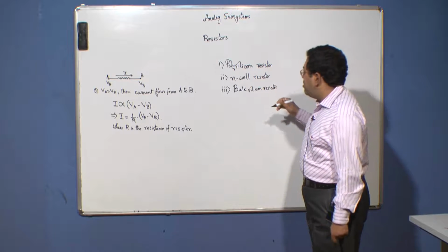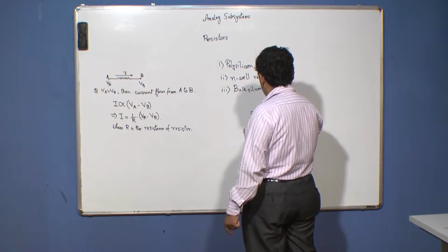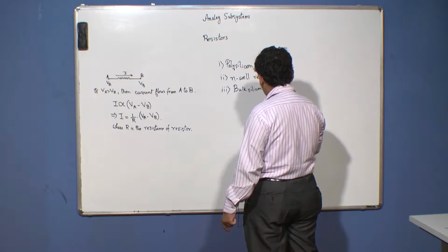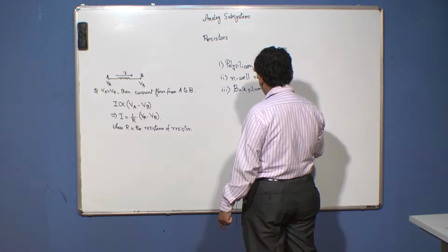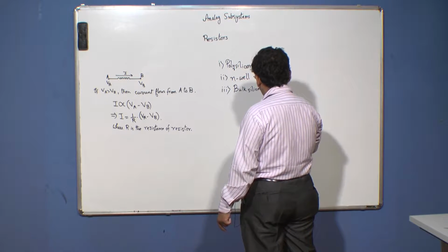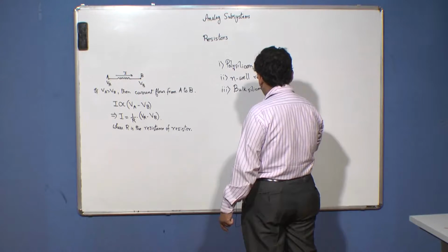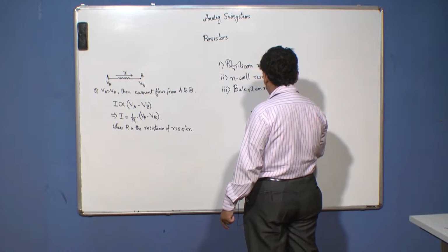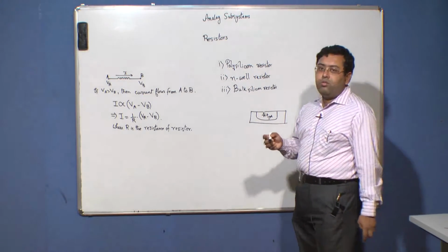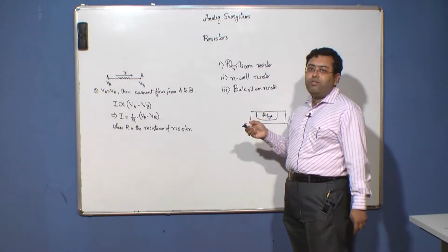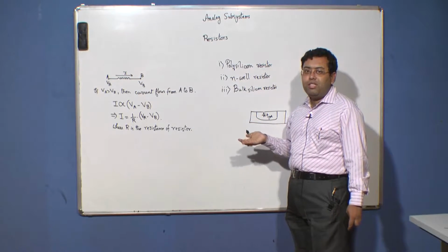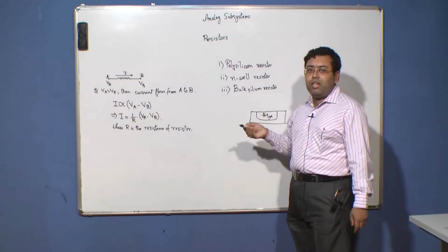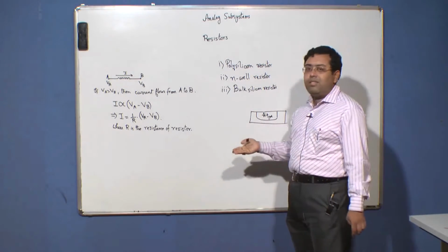We can have a doped silicon wafer, where a part is densely doped with donor impurities, and depending upon the doping density, the resistance is going to vary. That means, as you go on increasing the doping density, there is more and more abundance of electrons in this part of the semiconductor wafer, and therefore the resistance will come down.